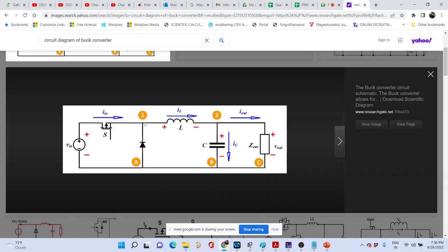You are getting my point? Say at point 1 it is 5 volt, and at the gate point it is at 10 volt. So what is the potential you are applying across VGS? That is the voltage drop between the gate and source.